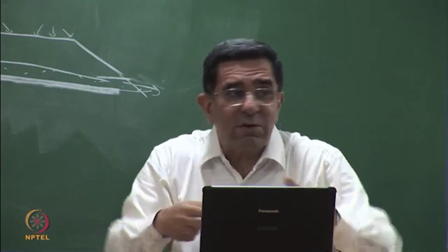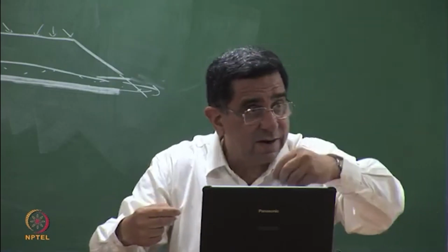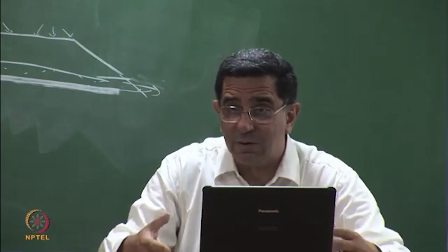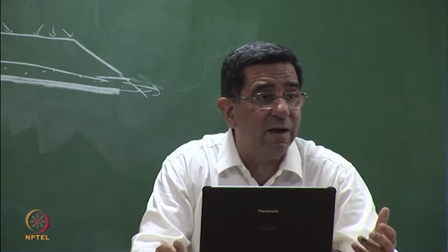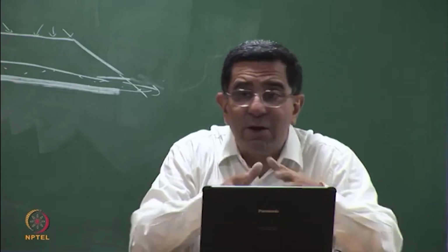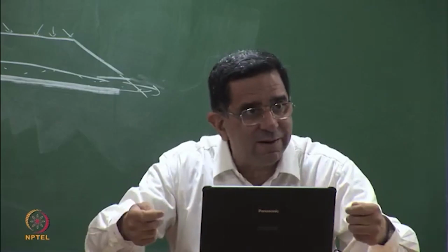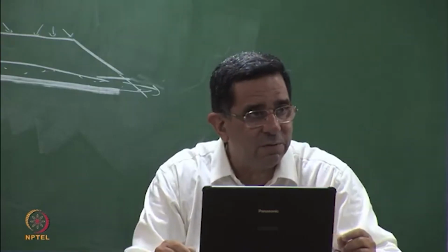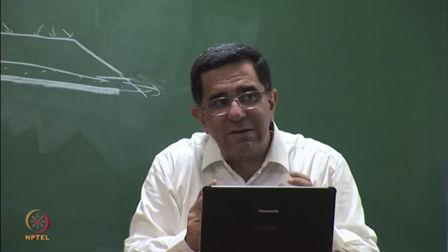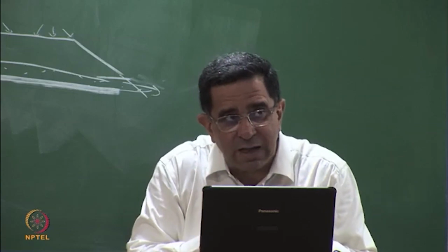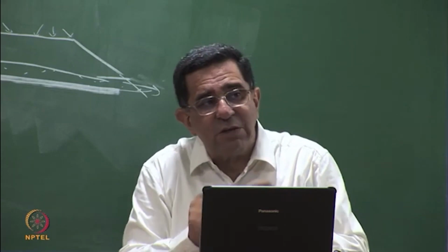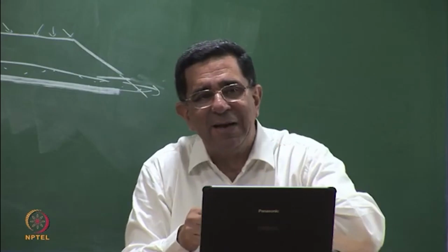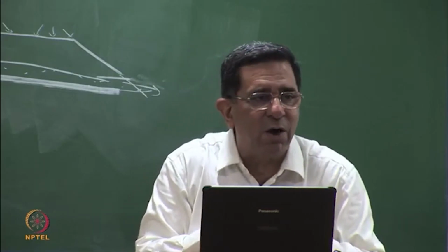So as geotechnical engineers, you can say, fine, if it is sand, yes, I can inject it, I can make a well, I can pump in the water, but if it is clay, it's not going to go. You can do hydrofracturing. You have done that in ground improvement, like make a root-like structure. But then your design should be like that. Your spacing of the wells has to be very close together if you are going to have overlapping hydrofractured points. So as geotechnical engineers, it's our role that we must be able to tell. You see, in situ injection and in situ grouting is so magical. I can take cement, I can inject it into the ground, and I can make soil into rock. How does it sound to you?